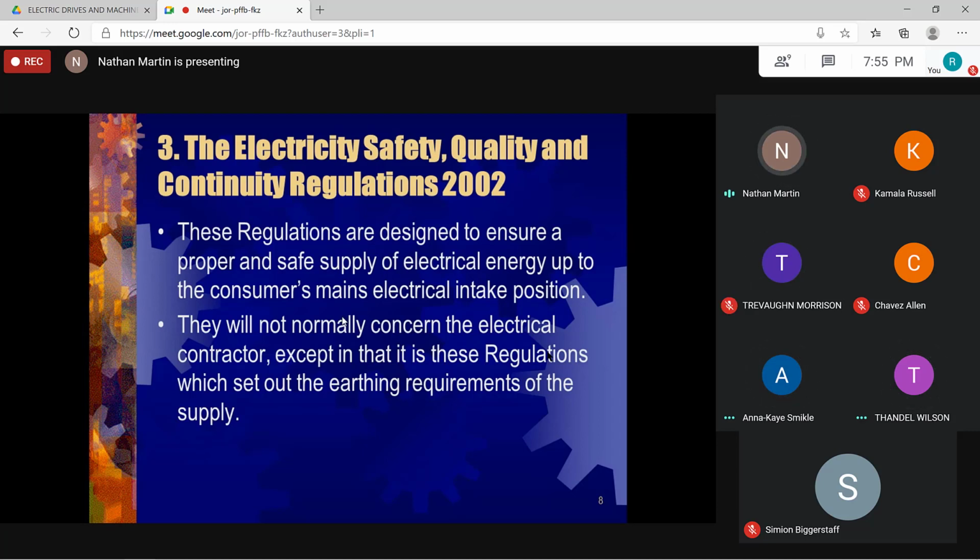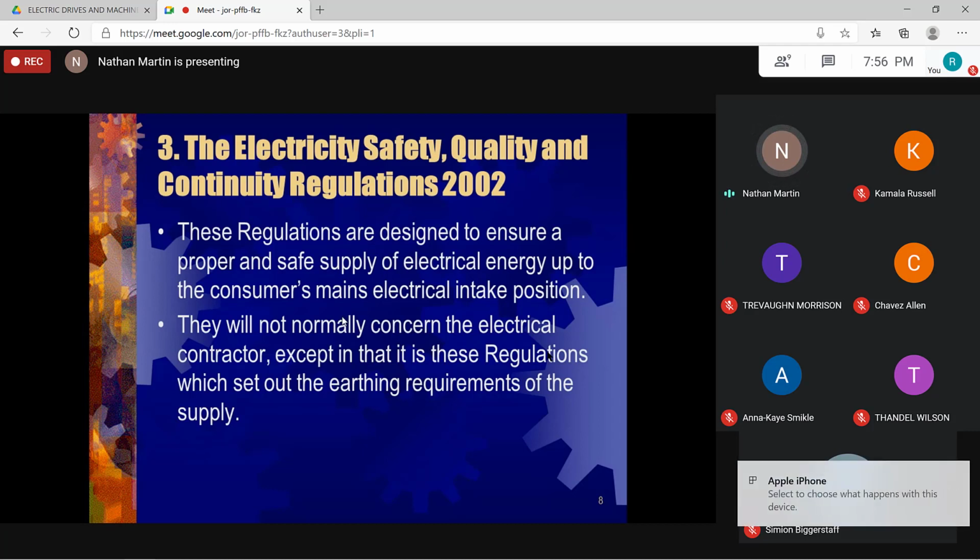All right. So you see, you guys know the stuff already. That's why I'm bringing it out. So that's one of the main purposes of the earthing installation: for the high current to flow so the breakers can trip, because the breakers are rated at particular values, right? 15 amp, 20 amp, 30 amp, 40 amp, 50 amp, 60 amp, and so on.